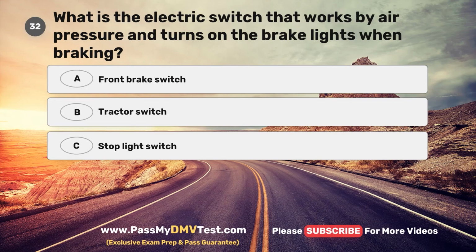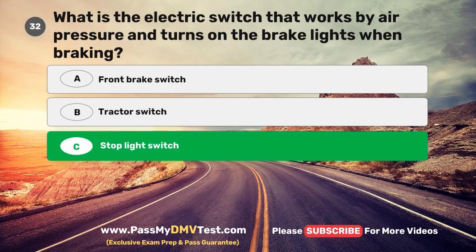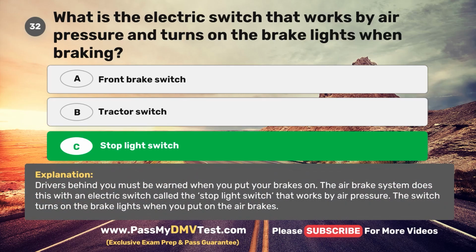Question 32. What is the electric switch that works by air pressure and turns on the brake lights when braking? A. Front brake switch. B. Tractor switch. C. Stop light switch. The correct answer is C. Stop light switch. Drivers behind you must be warned when you put your brakes on. The air brake system does this with an electric switch called the stop light switch that works by air pressure. The switch turns on the brake lights when you put on the air brakes.